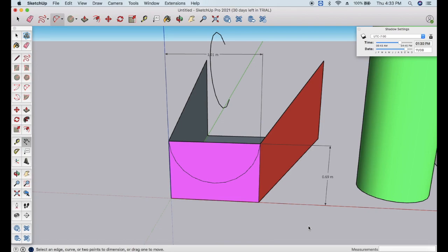Remember, for just checking it during your diagram, you can use the tape measurement tool. Dimension tools can be used while giving the dimensions and putting them in your diagram. If you are doing a scaling in your diagram and want to change it, then use the text tool to change this basic dimension, because this dimension will be given in meters or inches, whatever you choose. In our design we have chosen meters, so it will give you the practical, exact value. The scaling part needs to be calculated from your side and put in through the text command, right?